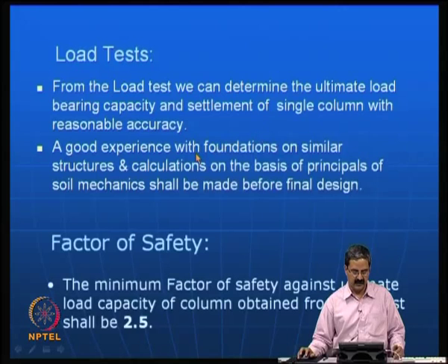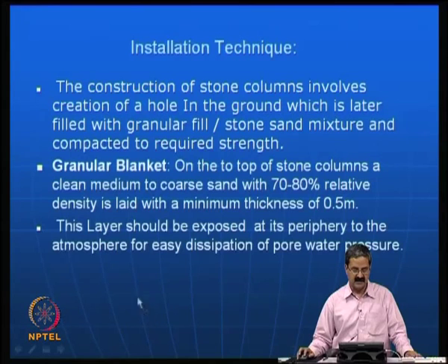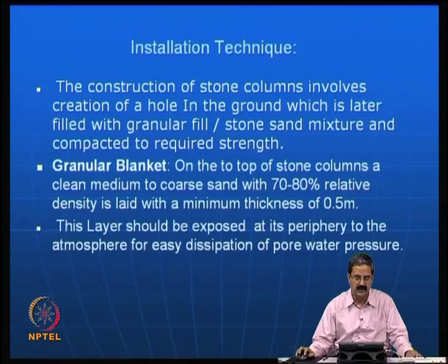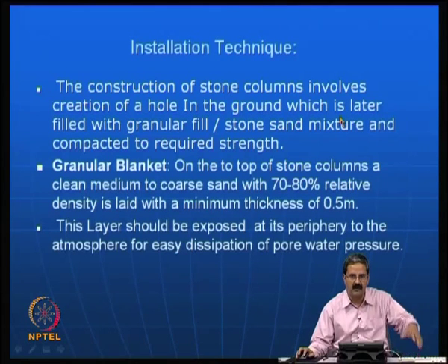settlements with reasonable accuracy. A good experience with foundations and similar structures and calculations on the basis of principles of soil mechanics is important. The minimum factor of safety should be about 2.5, and for the installation techniques, we have seen some construction procedures by the Keller group. Of course, people have been using these construction techniques particularly in small projects, where big contractors may not come. So, people try their own technique of forming a hole and then putting the sand material and compacting it.